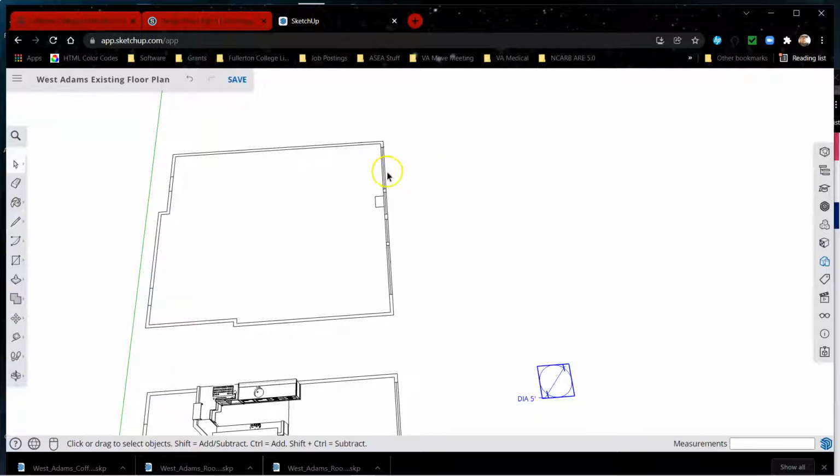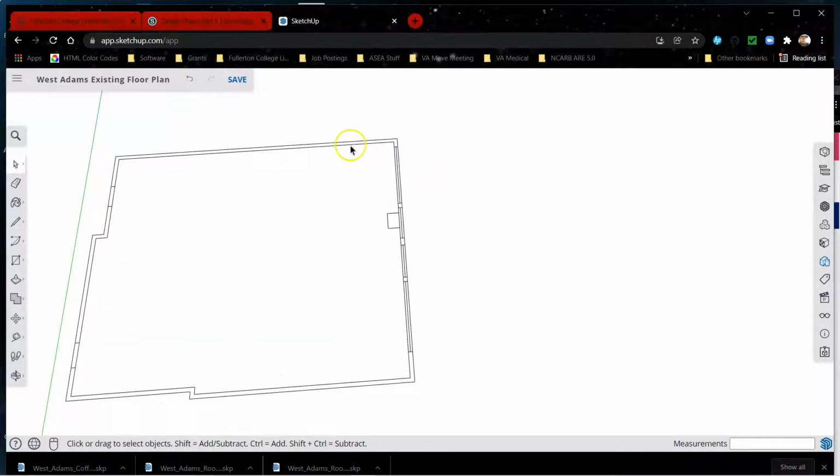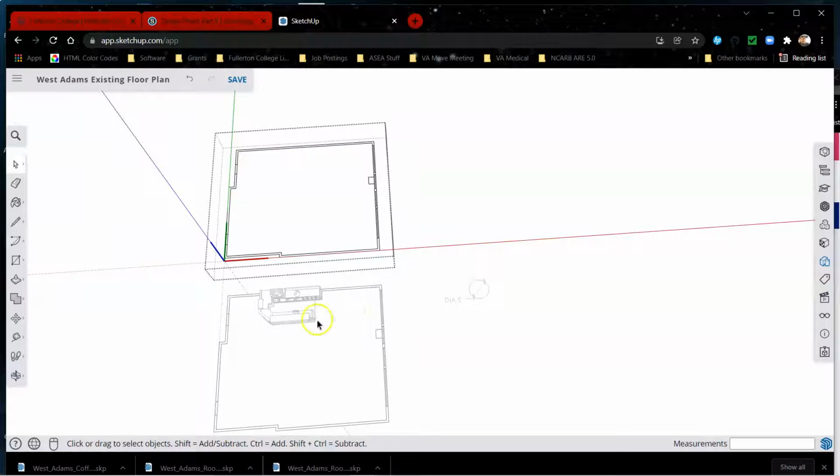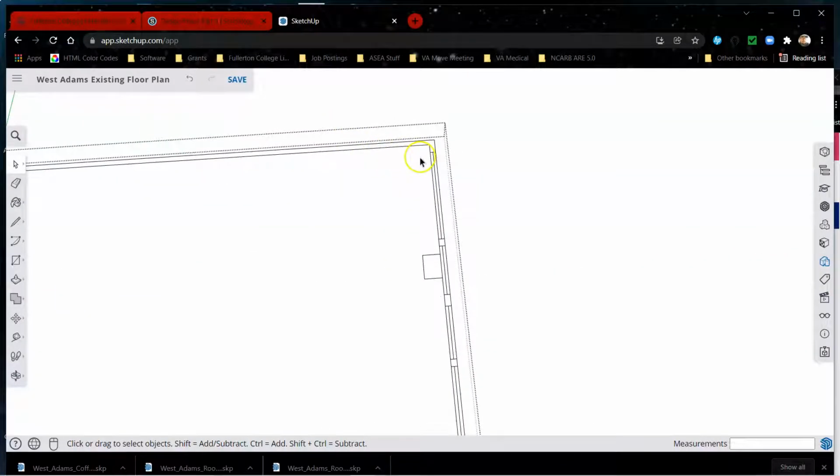I want to make sure that, again, we're just setting furniture on top of this. This is the original floor plan. Let's go 5'6". I like to go 6 inches above. There you go. And so SketchUp is kind of predicting I'm going to go 5'6", 5'6".